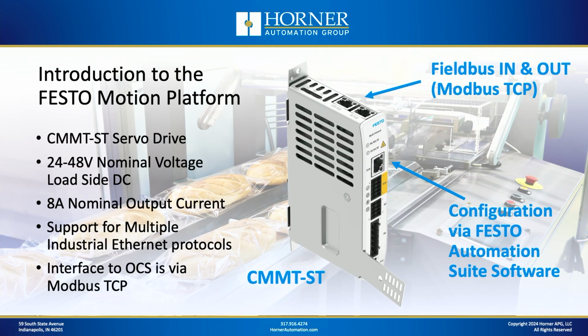Okay, so some highlights of the CMMT-ST product. You configure it using FESTO Automation Suite software, and that's accessible from the front via a dedicated configuration port for Ethernet. And then in terms of the runtime communications, that's accomplished through Ethernet ports on the top of the unit. You've got an in and an out for the field bus. And we'll be using Modbus TCP today for our demonstration, but the drive also supports a variety of other field bus protocols that are Ethernet based.